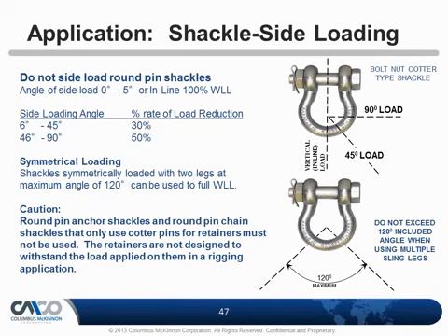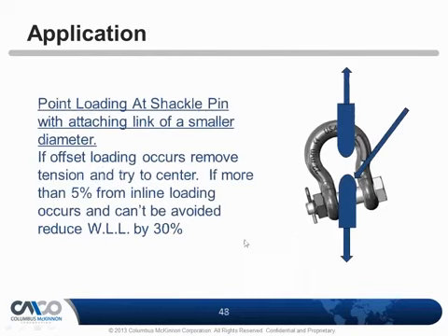And once again, we caution against using round pin shackles. Those are the shackles that do not have any type of threaded connection. They're just a cotter pin retainer. We highly recommend that you don't use those for overhead lifting. Keep those for tensioning or securement and towing.